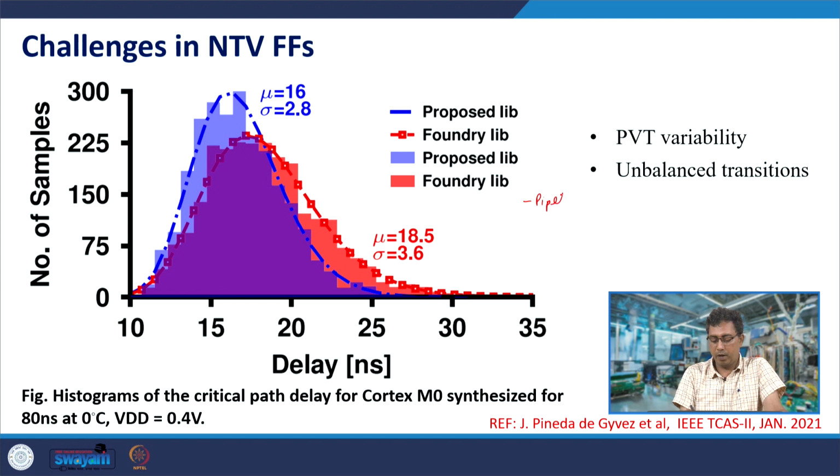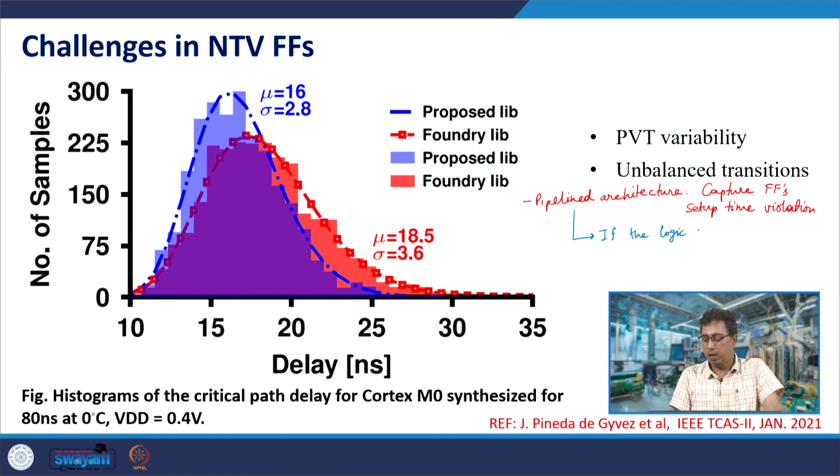In a pipelined architecture, the capture flip flops can have setup time violation, and to counter this problem, if the logic depth is reduced, hold time violations can result.